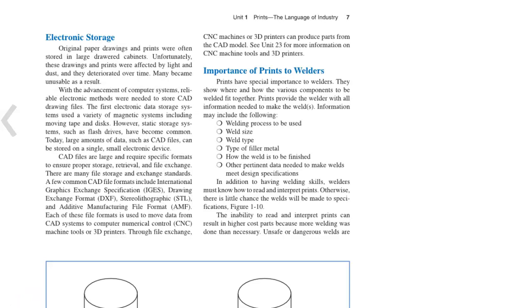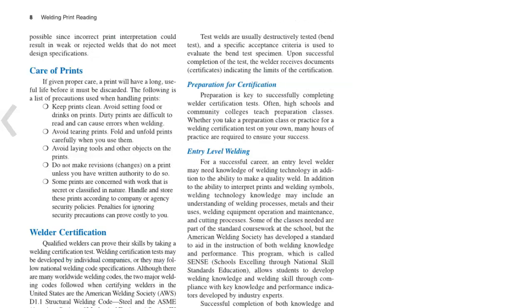In addition to having welding skills, welders must know how to read and interpret prints. Otherwise, there is little chance the welds will be made to specifications. The inability to read and interpret prints can result in higher cost parts because more welding was done than necessary. Unsafe or dangerous welds are possible since incorrect print interpretation could result in weak or rejected welds that do not meet design specifications.